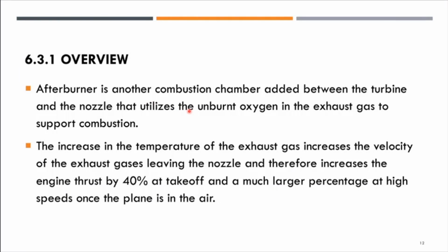So the increase of the temperature of the exhaust gas definitely increases the velocity of the exhaust gases leaving the nozzle, and therefore increases the engine thrust by an additional 40% at takeoff and a much larger percentage at high speed once the plane is in motion.